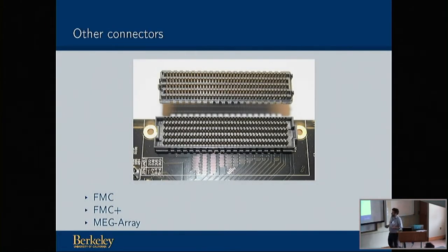So it's worth noting that while you'll see a lot of ZDoc connectors in CASPER, as I say, that connector is largely deprecated. In fact, I think our manufacturer, Digicom in Oakland, probably has the final stock in the world of those connectors. You will see, in other ADCs, both those coming out of the collaboration and those available from commercial suppliers, a bunch of other connectors: FMC, FMC+, which come in large pin count versions and small pin count versions, and Mega Array, which is what you'll see on the SKARAB. All of these are just physical connectors that provide some connectivity from one board to another and provide different numbers of pins, different speed limits about how many bits per second you can transfer through them reliably. And so you'll see a lot of these appearing on future ADCs in one form or another.